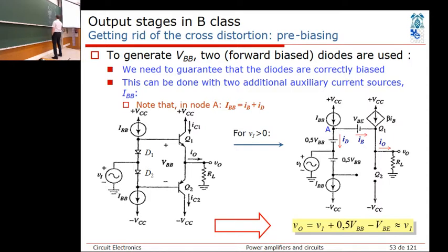This is the input, and then originally we have the required operational amplifier output here. But now, basically, due to that biasing diode, you drop it closer to that point. And same thing actually on the negative cycle. So now we have a nice linear operational amplifier driven AB class amplifier with virtually no crossover distortion.